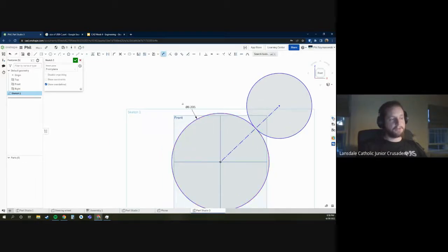And for the gears that we use, they use a system called diametrical pitch, which means how much bigger the sprocket gets based on how many teeth it has. It's a little bit confusing, but essentially, if you have a 20 tooth gear and a diametrical pitch of 20, you will have a sprocket or a gear that is exactly 1 inch.